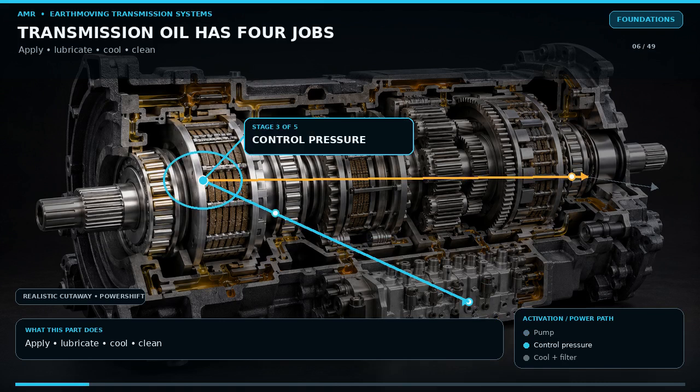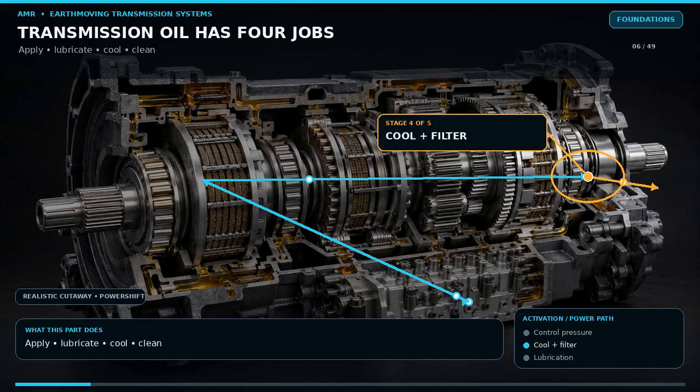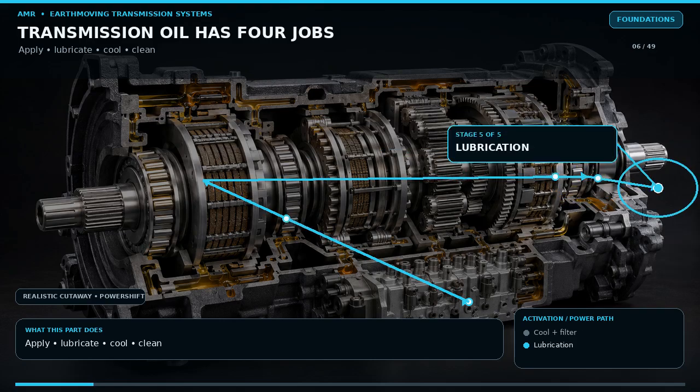The correct oil level, viscosity, and specification are essential. Low oil can draw air, causing delayed engagement and pressure fluctuation. Too much oil can foam and overheat. Wrong oil changes friction behavior and shift quality. Contaminated oil can stick a precision spool or damage a pump. Always check oil at the specified temperature, engine condition, and machine position because the correct procedure varies by model.